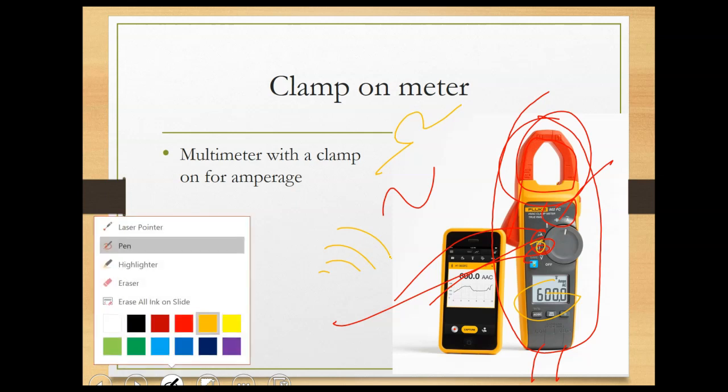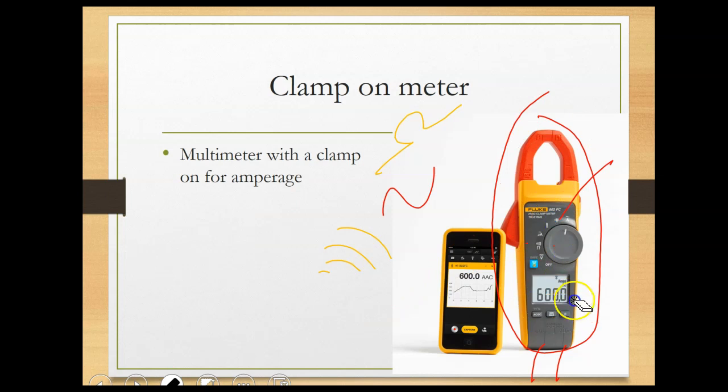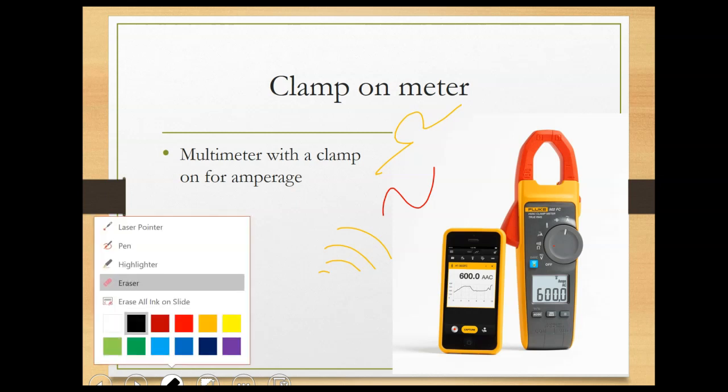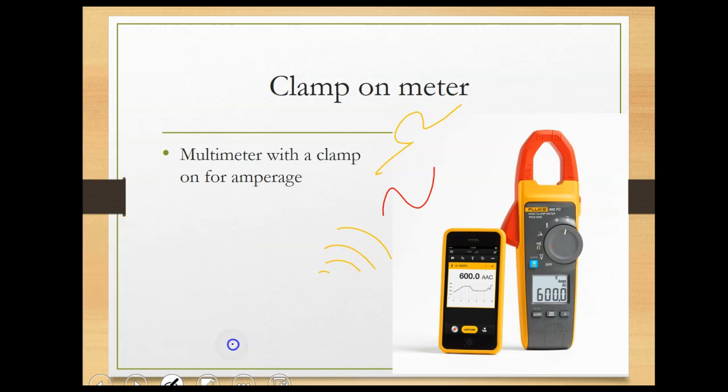And again, I've seen this mistake before where people just mix and match the clamp-on and they wish for voltage, but it's not going to happen. The clamp is only for the amperage. So amperage is the clamp. Volts, you're going to use the leads here. As you see, there's something that is common, which is neutral, and the power. And that's all to it.